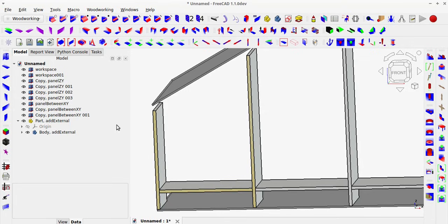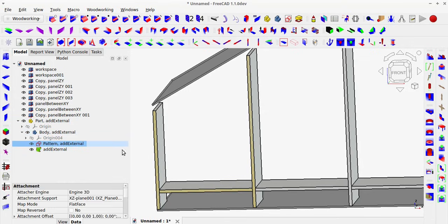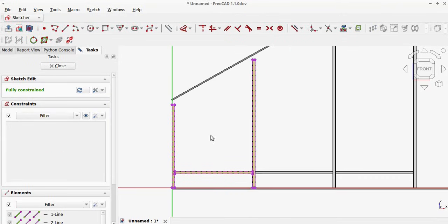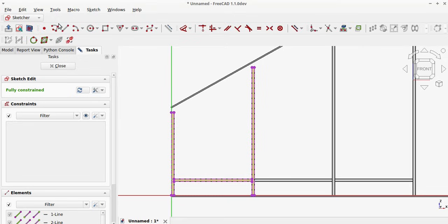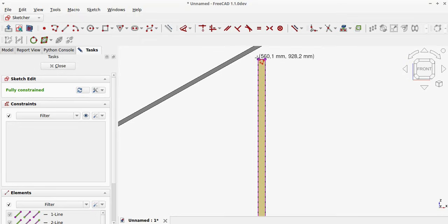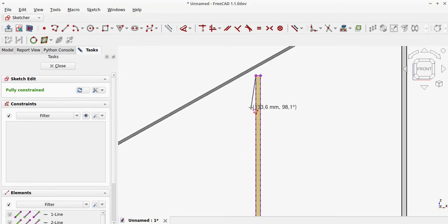If you want greater precision in creating fronts and their parameterization, simply use the Add External tool. This tool will create a new structure with a sketch and references to selected faces. Simply edit the sketch and draw the front. Construction lines can also be used if there's no way to anchor the front shape in a given location.